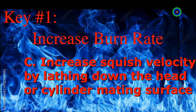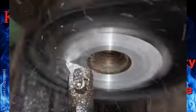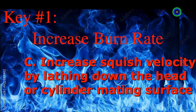The amount you lathe off of the head or cylinder top is very minimal. It's usually just a few tenths of a millimeter, less than what you would if you wanted a sizable increase in compression. But to do this, you should know what the squish velocity is to begin with and what the recommended amount of velocity is to compare it to. And you can do that with my squish velocity calculator.